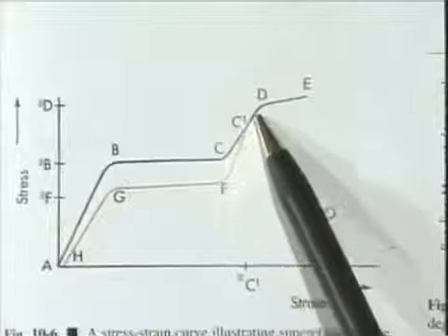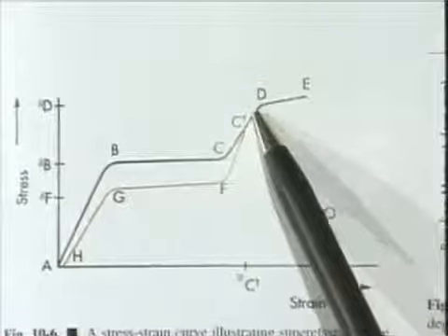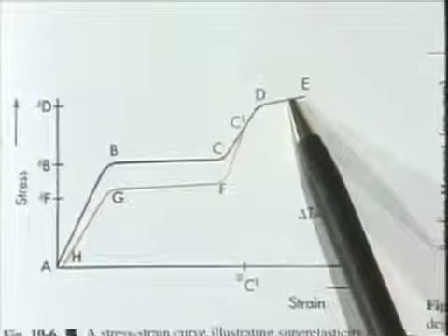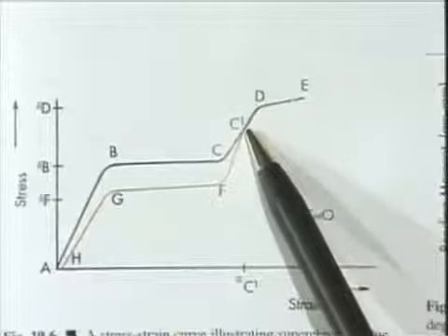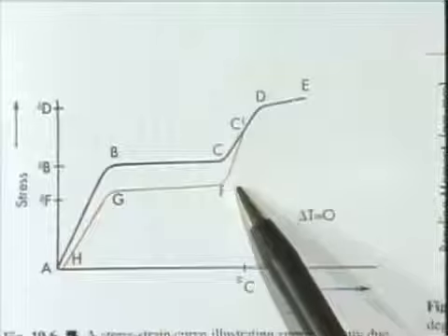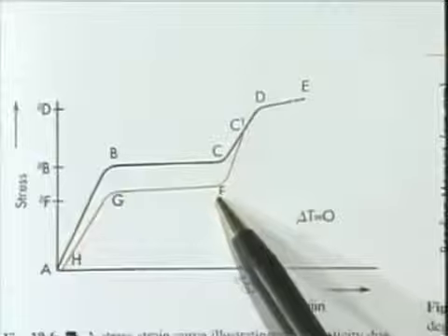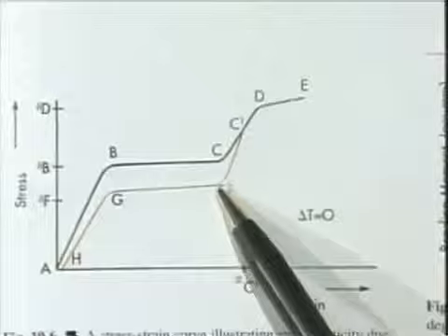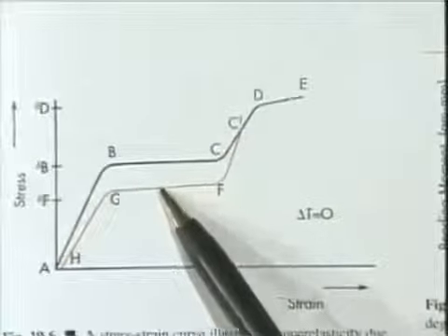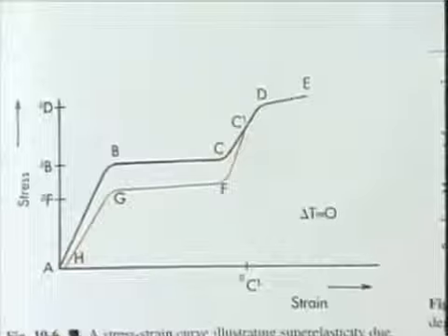And now we're looking again at a portion of a curve that looks just like that traditional force deflection or stress strain diagram. It's got a shoulder. If we bent it far enough, it would break. If we let it straighten itself out, it does another interesting trick, and that is it doesn't retrace its steps along that original curve. Instead, it goes down to here, and at this point marked F, we get a reverse transformation. Our martensite turns back into austenite, and once again we get a very linear portion of this force deflection curve, and then finally it goes back to almost where it started from.